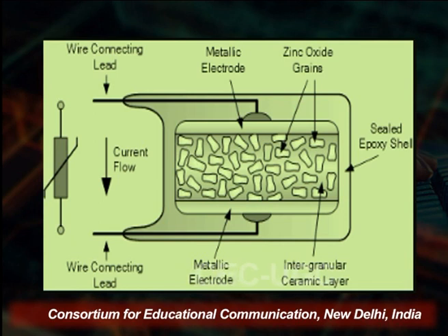Now, to select the correct MOV for a particular application, it is desirable to have some knowledge of the source impedance and the possible pulse power of the transient for the incoming line or phase bond transient. So, selection of the MOV is a little more difficult, as generally the characteristics of the power supply are not known. There are many factors on which the selection of the metal oxide varistor depends. In general, MOV selection for electrical protection of the circuit from power supply transients and spikes is often little more than an educated guess.